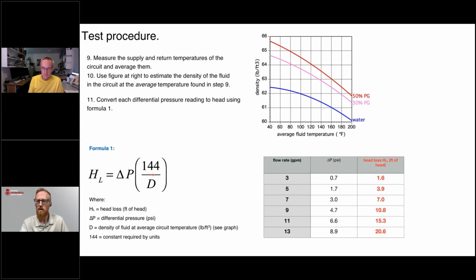Thanks, sir. Let me get this one pulled up. Do you still have to plot the system characteristics if you measure all the piping, fitting, etc. to determine your head? In which case, you could just use delta T and electronic flow meter.